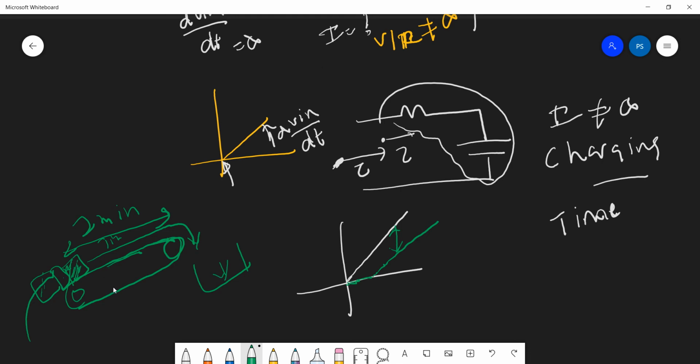And what is this time delay in the context of this circuit? The RC time constant. So you apply the input, but you can expect the output after some time. It means there will be a constant delay, and this will be decided by the time constant of our circuit. So that's the way of analyzing your circuit in terms of impulse, step response and ramp response.